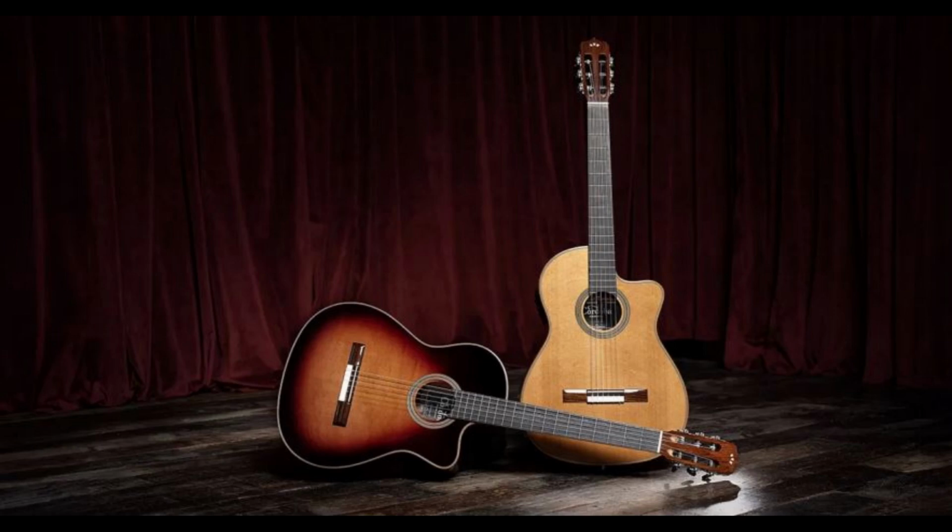On an instrument correctly adjusted for intonation, the actual length of each string from the nut to the bridge saddle is slightly, but measurably longer than the scale length of the instrument. This additional length is called compensation, which flattens all notes a bit to compensate for the sharping of all fretted notes caused by stretching the string during fretting.